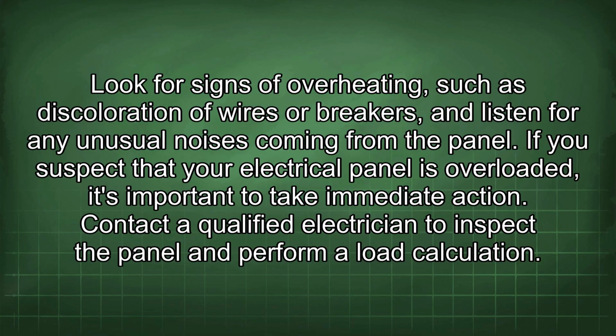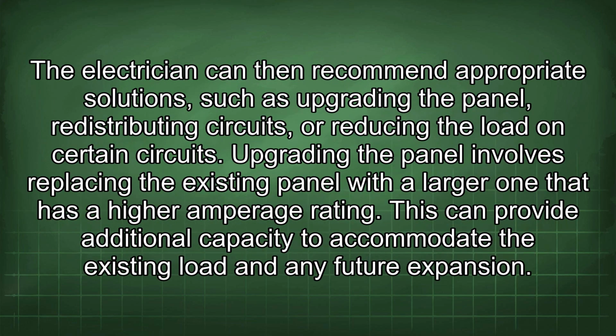Look for signs of overheating, such as discoloration of wires or breakers, and listen for any unusual noises coming from the panel. If you suspect that your electrical panel is overloaded, it's important to take immediate action. Contact a qualified electrician to inspect the panel and perform a load calculation. The electrician can then recommend appropriate solutions, such as upgrading the panel, redistributing circuits, or reducing the load on certain circuits.